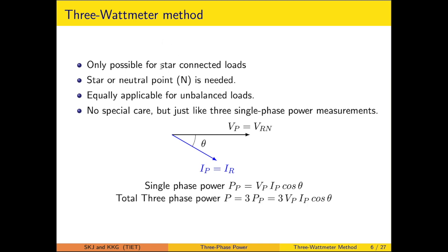However, this particular method is possible only for the star connected load because we need the neutral point, which is the star point. This method is equally applicable for the unbalanced load. As mentioned previously, this is just like 3 single phase power measurements. So we will be able to analyze it on the single phase basis.